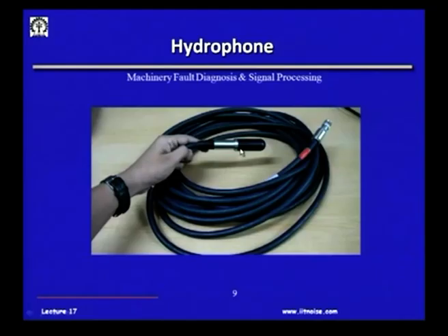If you want to measure noise deep in the ocean, you can have a hydrophone just dropped into the ocean, with a long cable coming from it, and on the ship you could possibly connect it to an amplifier and then see the output. Such sensors are known as hydrophones. You could have an array of hydrophones to sense from which direction the sound is coming, and particularly in ship hulls and submarines, at the front there are a lot of such hydrophones which actually work as sonars.